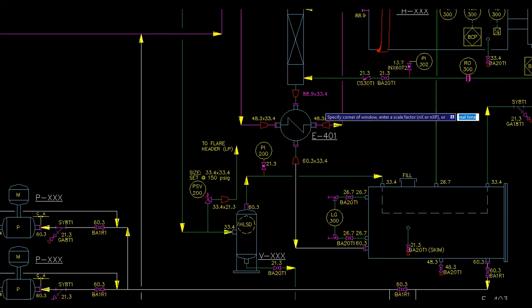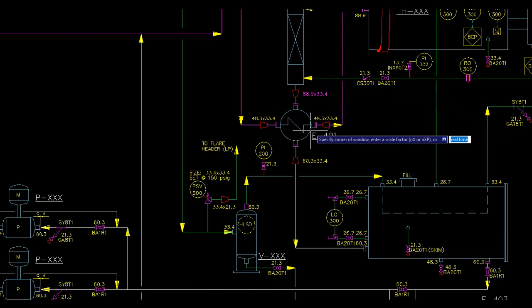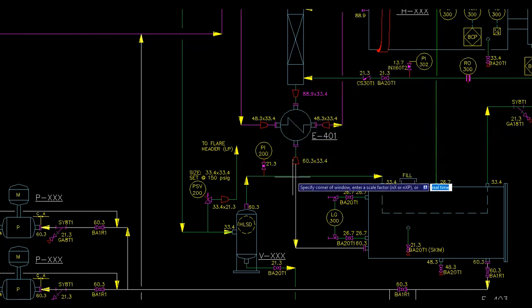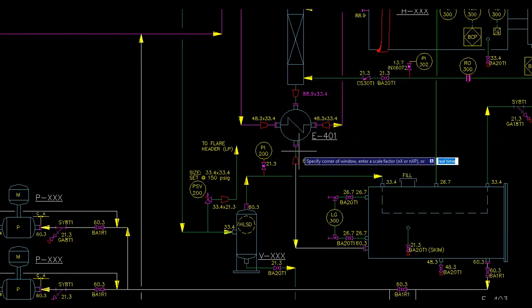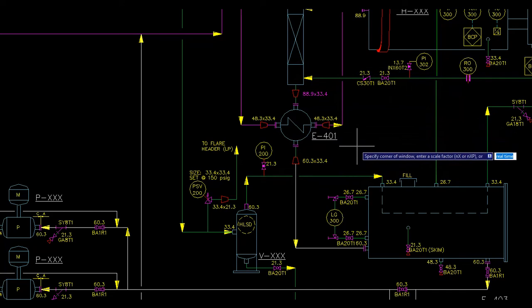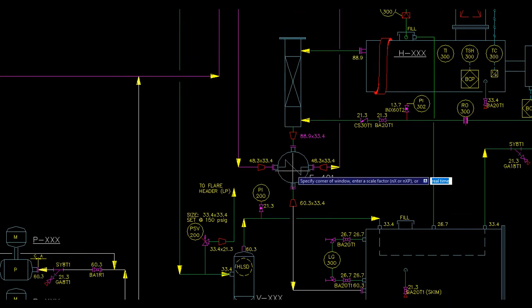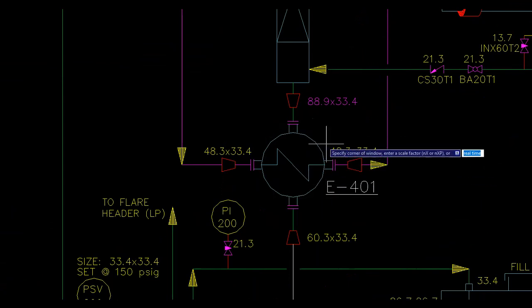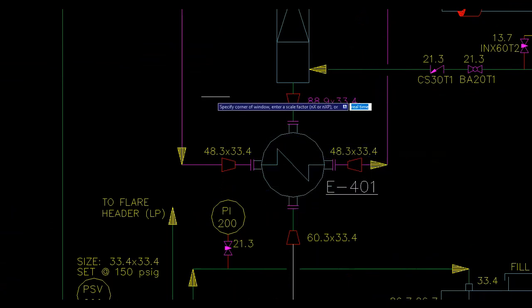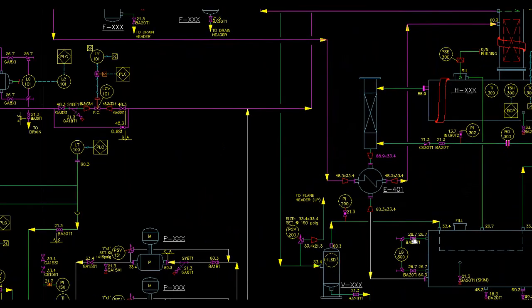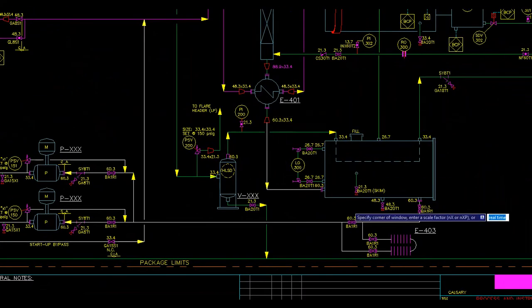In the exchanger, the surface area for cooling glycol is more than the surface area for heating. Cooling glycol is more important than heating glycol, since there is no other opportunity for glycol to cool down to the contactor's temperature. The glycol reservoir is usually part of the package with the reboiler.